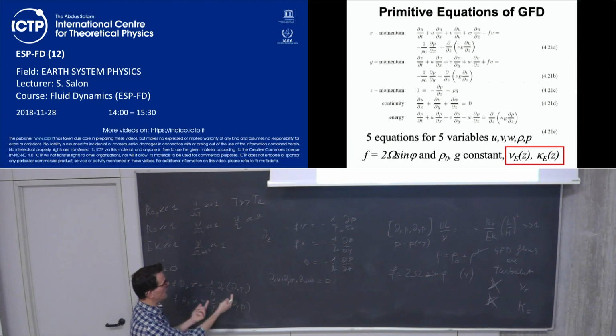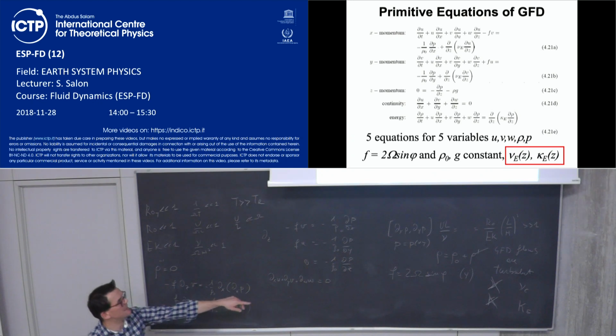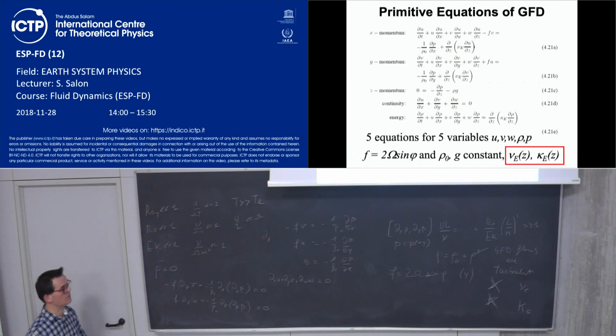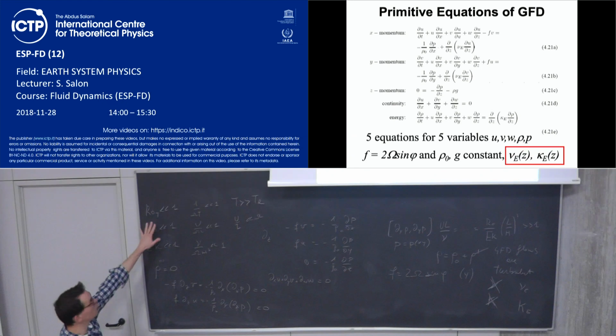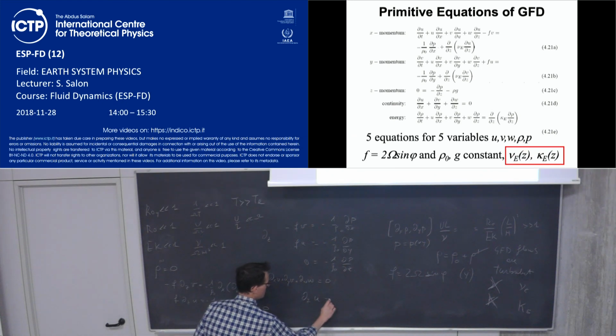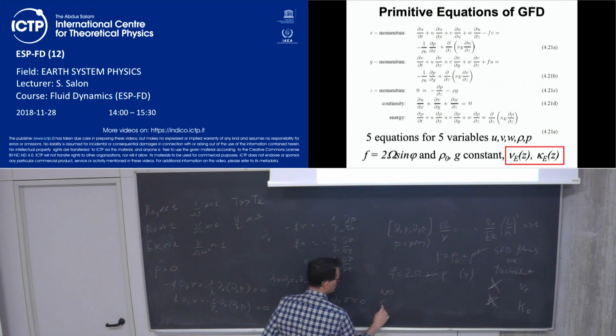You know quite well that we can exchange the order of derivation. So we can make first the derivative over z, but the derivative over z of the pressure is 0. Wow, this is a big result. So we have obtained that with this hypothesis, our flow has no shear.